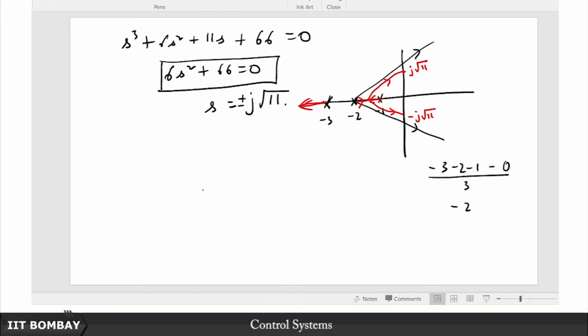from a different perspective. So for example, if you have a second order underdamped system, a typical second order underdamped system would have a pair of poles like this. Now we also talked about what happens if there is an additional pole or zero. My claim is, and we will see immediately from the root locus that it follows, that if you have an additional pole to the left here like this, it is bad for the system.